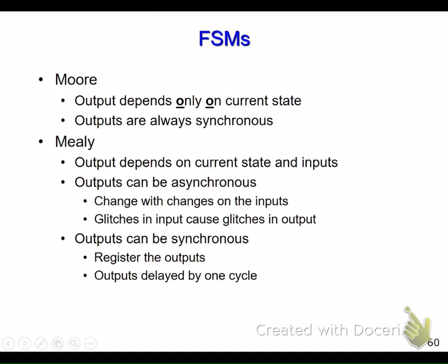So here it just describes whatever we mentioned, but one more thing I would like to highlight: in the Moore machine the outputs are always synchronous, but in the Mealy machine they can be asynchronous or synchronous. Do you know what the difference is between synchronous and asynchronous? Anyone know the difference? Yes? Basically, synchronous is controlled by a clock. But asynchronous can be at any time. Whenever you have your output, just show it to me. But if I'm saying with a clock,